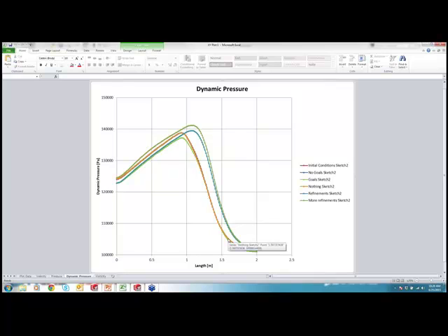It follows that one even more closely. And the initial conditions allows us to save CPU solver iterations to solve for the little dynamic effects that adjust these tiny little parameters a little bit, versus spending iterations trying to just develop a big flow field.